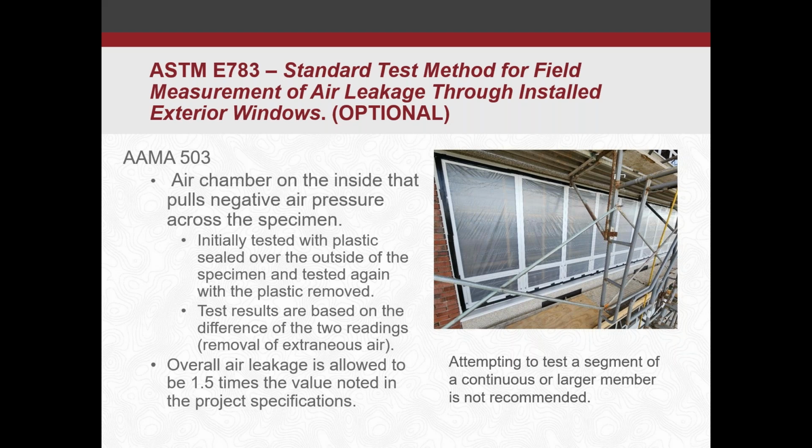So in this, the overall air leakage is allowed to be 1.5 times the value noted in the project specification. Similar to AAMA 502.